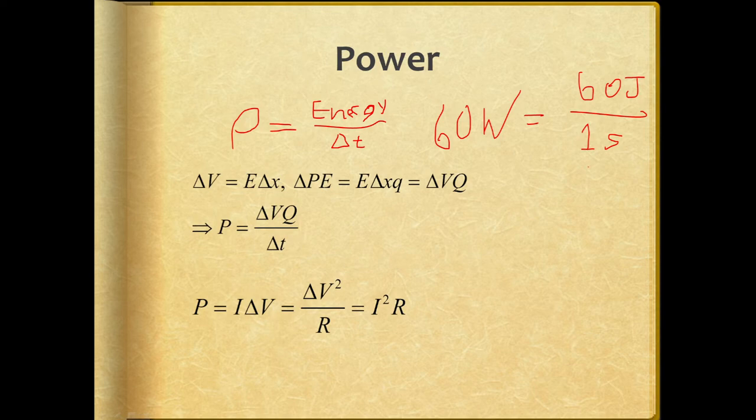The lights in the room may dim, or maybe certain devices just turn off when you turn the vacuum cleaner on. Because by adding the vacuum cleaner into the system, it starts taking energy out of the system that was previously going to other things. And if those other things aren't getting their required amount of joules per second to meet their wattage, they either dim and don't work quite right, or they might even turn off completely. So that's why that happens, and that's what the number of wattage represents when it comes to electronics. It's the energy per second it needs to remain active.